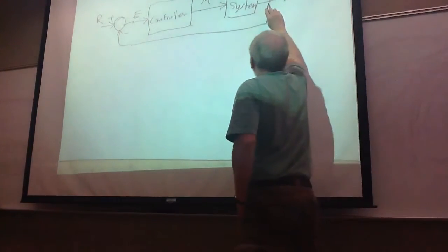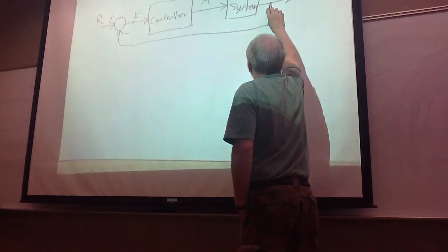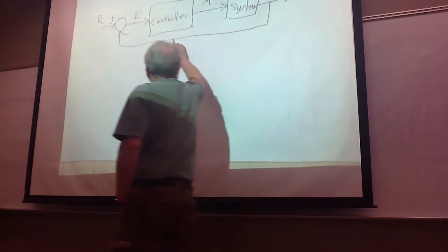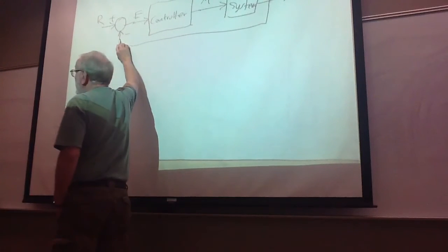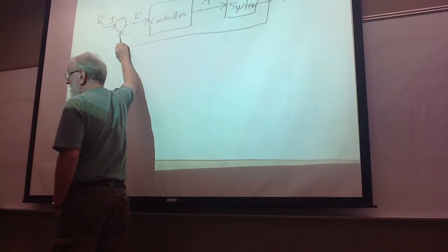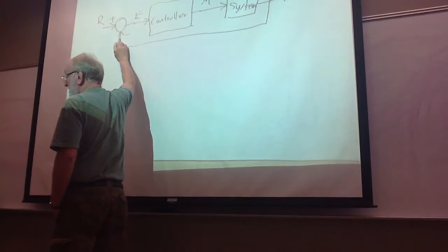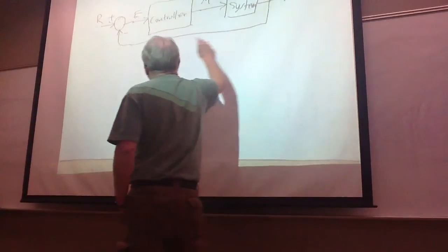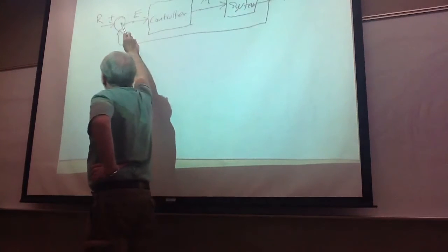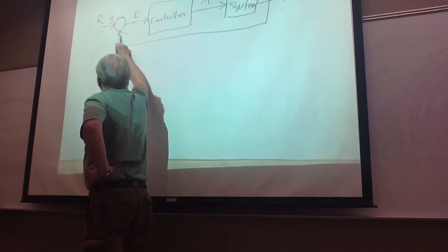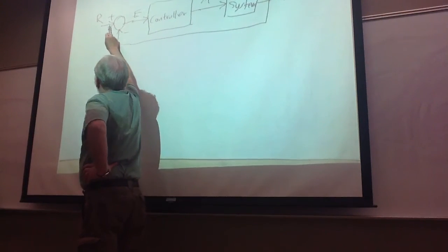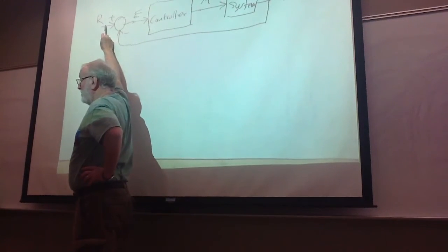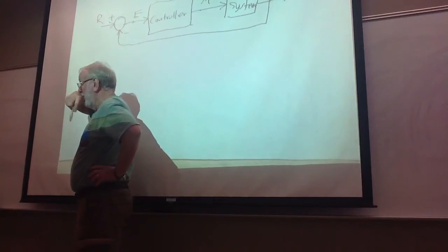So this is the temperature of this output, degrees centigrade, Celsius. Comes over here. What are the units of it when it gets over here? Same. They don't change units. Nothing changes when you're going through a wire like this or through a line like this. And then this minus sign means we subtract this from this thing. This thing here is the reference point, aka the set point.